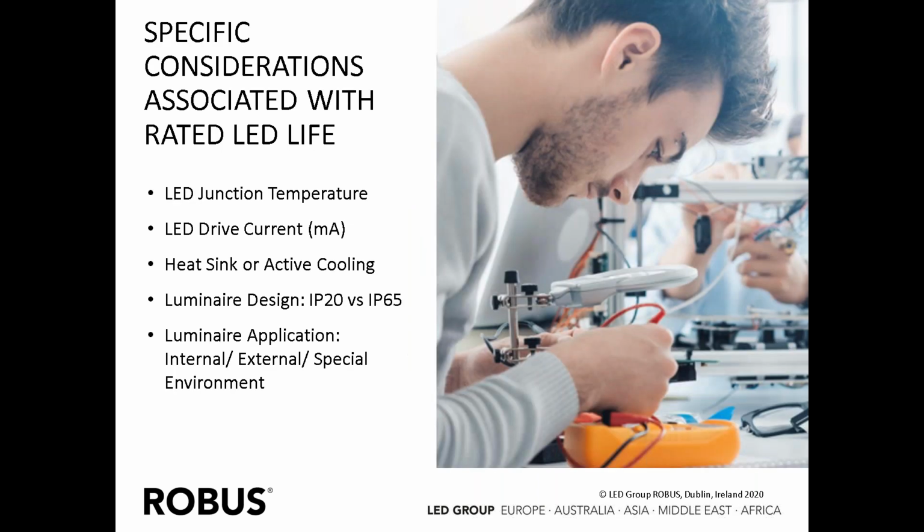Some specific considerations associated with the rated LED life is importantly LED junction temperature. That is the temperature within the actual LED chip, where the photons are generated, the PN junction as we call it.